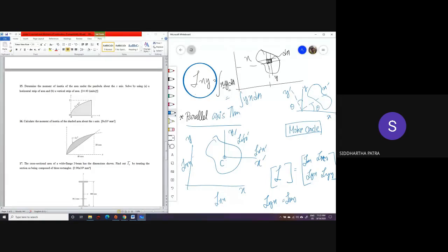With mass moment of inertia, that would be 3D. Okay, so it would be involving the z coordinate as well. And also there is something called stress, represented with the Greek symbol sigma, and typically thought of as the force per unit area, with the most general case a cylinder having been pulled by a force F over its cross-section area A. But that is not the only sort of stress that is there.